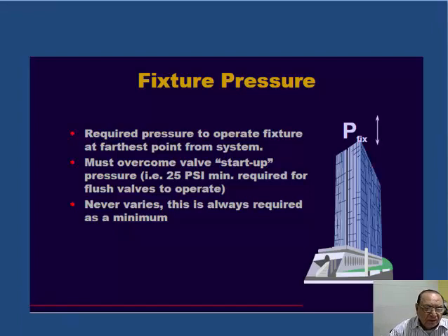Fixture pressure, this is what we are calling as a residual pressure also, and it shall be varying according to the applications of the kind of fixtures. Like washing machine require more pressure, and dishwasher require different pressures. Flush valve operated system require different pressures. So that is actually considered, and generally we term this as a residual pressure.